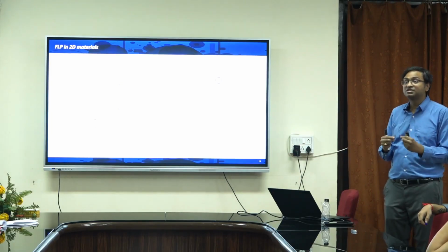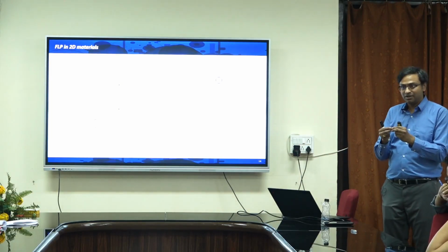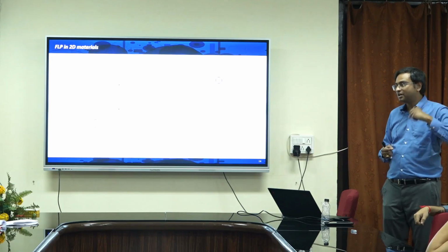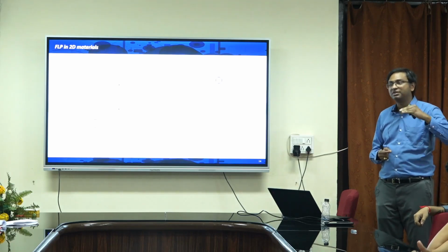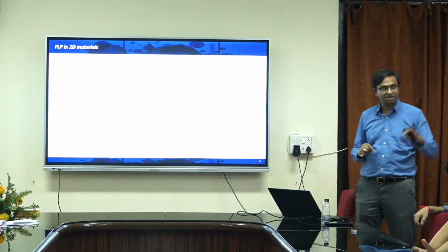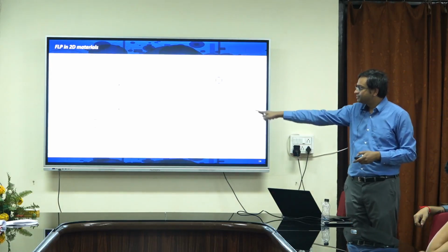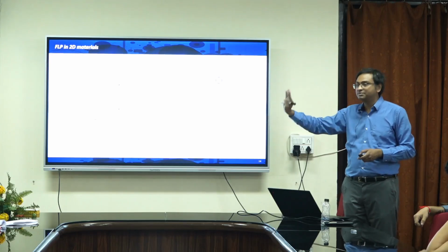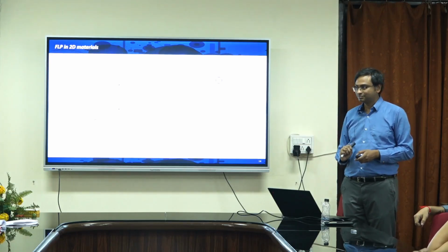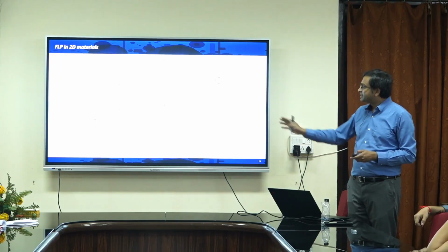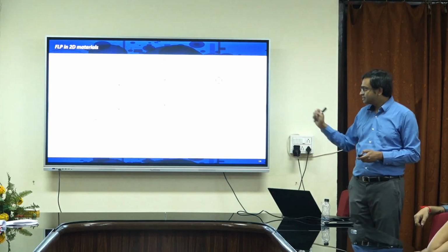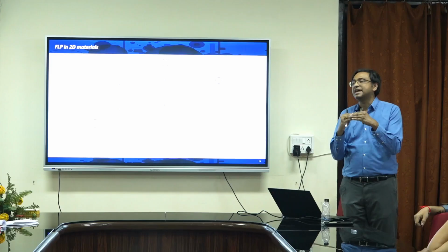right. So this is called Fermi level pinning, because just by changing the work function, I am not able to change the Fermi level of the metal with respect to the semiconductor, which we just drew, okay. That is a severe problem, you see. So you only get NFET even with platinum contact, right. The same thing happens for tungsten selenide. In tungsten selenide, this pinning happens mid gap.